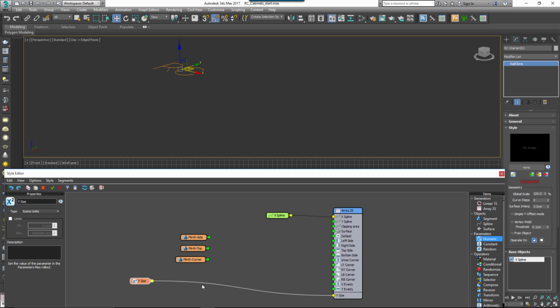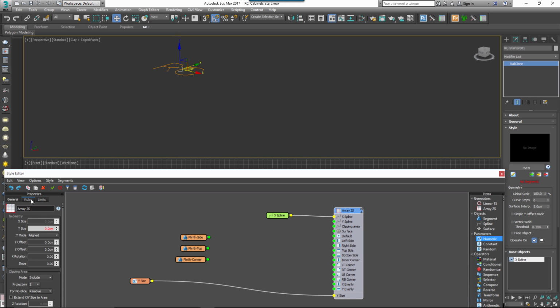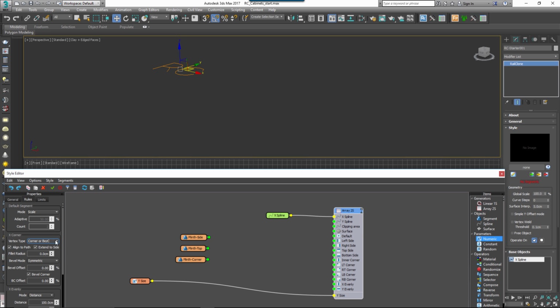Go into the generator's properties and set the default mode to scale. This is so that the plinth segment will stretch along the path of the spline without getting sliced. You should also change bevel mode to none to prevent the spline being sliced every time there's a vertex. This will maximise the amount of instancing that takes place as slice segments render a static geometry.